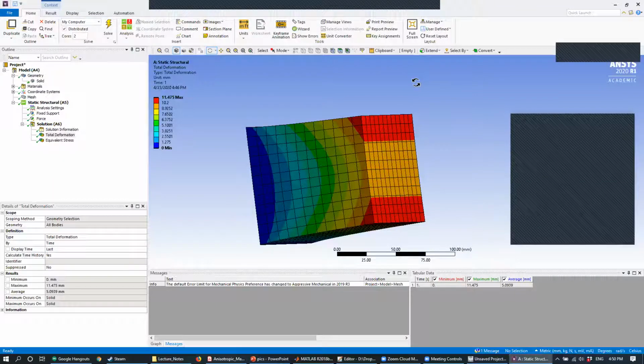But I think there are some assumptions you can make where you can probably model the 3D printed material as orthotropic, because anisotropic materials are very difficult to use, since you have so many constants that you need to define. So if you make some assumptions, you can probably model it as orthotropic, and I think it would be somewhat reasonable. It wouldn't be perfect, but I think it would be pretty reasonable for most cases. Yeah.